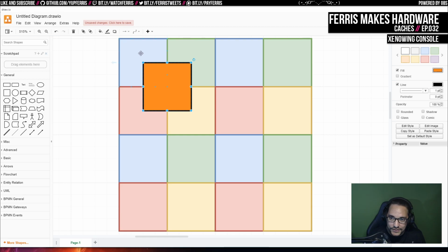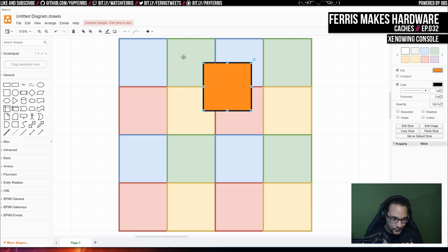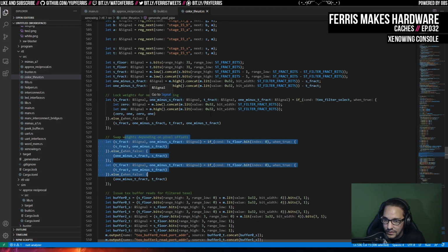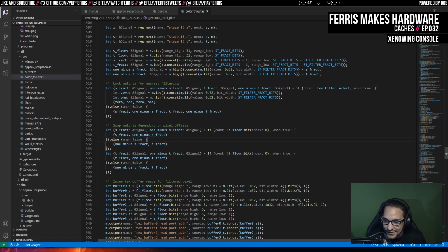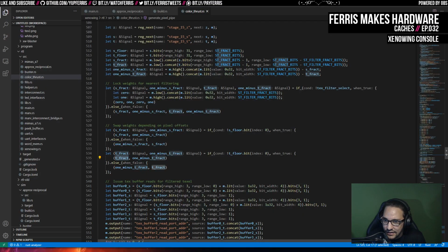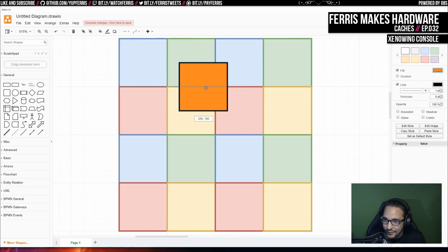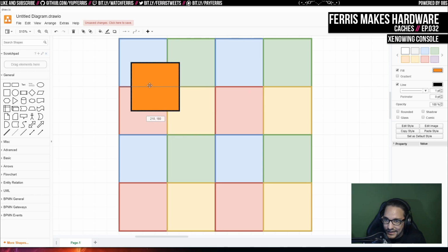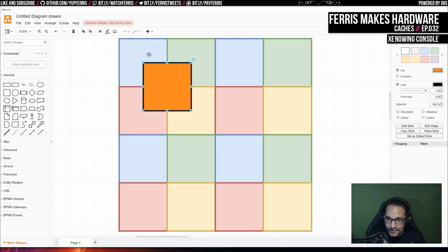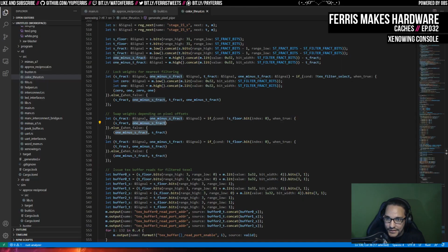Here, the top left pixel is from the blue buffer, but here the top left pixel is from the green buffer. So there's some extra stuff where I will actually swap the weights instead of swapping the pixel data. For these fractional values, that's how I swap this. I take the lower bit of the whole value, which swaps as I go like this, and then same with T. I swap the fractional components around if that lower bit is set. Because these fractional components are like 4 bits, whereas the color data is like 32 bits, I have smaller muxes that way.